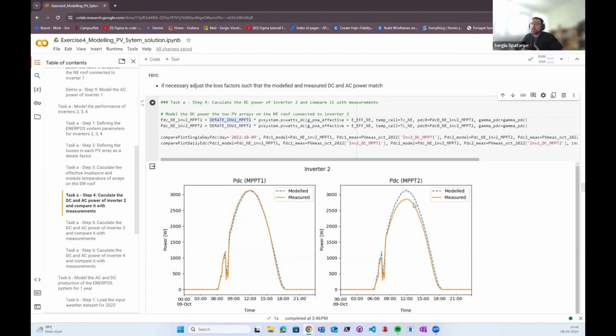Now, unless I go on site and determine what happened, what could have happened? One possible thing is maybe some panels were removed, or they are damaged or short-circuited, or maybe some panels are more degraded than others, specifically to this inverter. So something has happened that caused the whole array to generate less power.